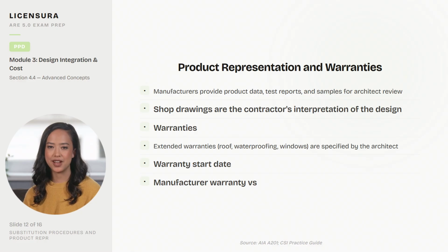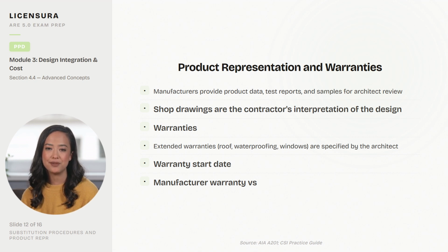This table identifies 5 common coordination errors between disciplines. Architectural and structural drawings showing columns at different locations are prevented by sharing a BIM model with a linked structural grid. Ceiling height conflicts with duct routing are prevented by establishing plenum depth early and running clash detection.